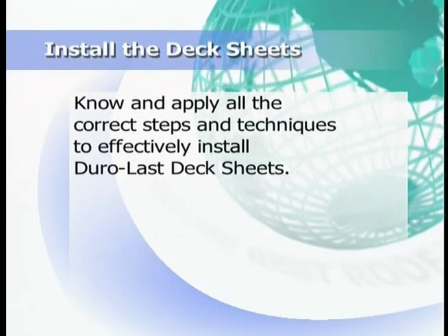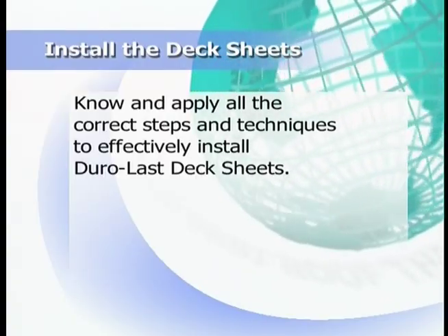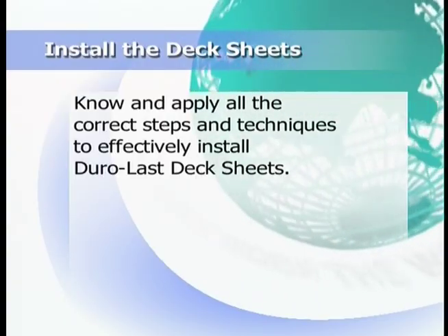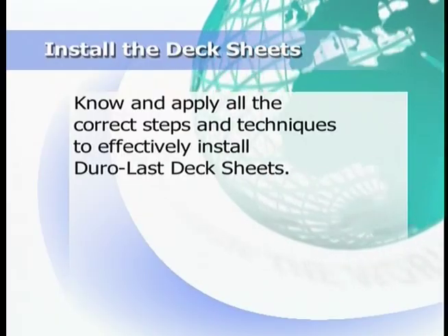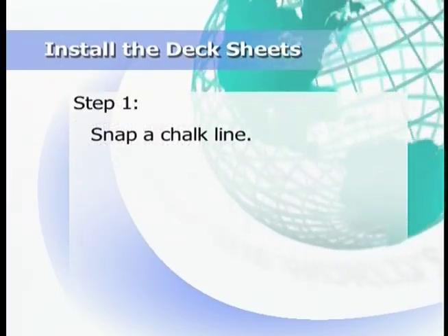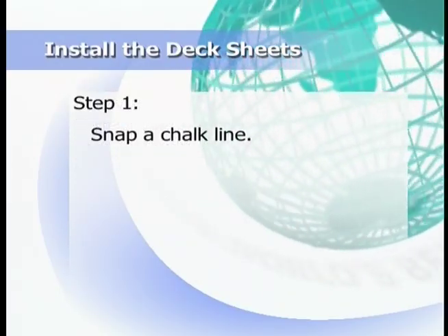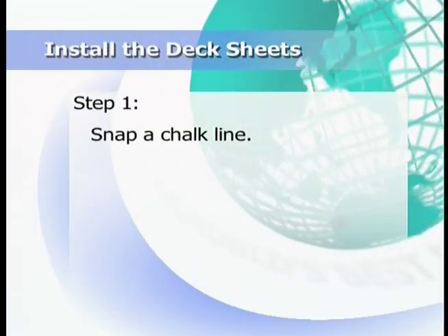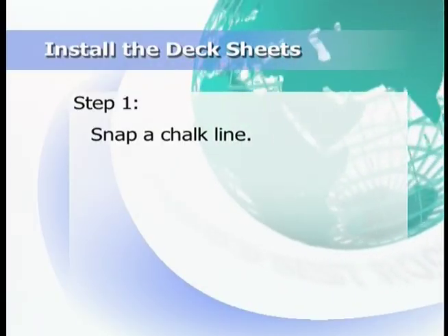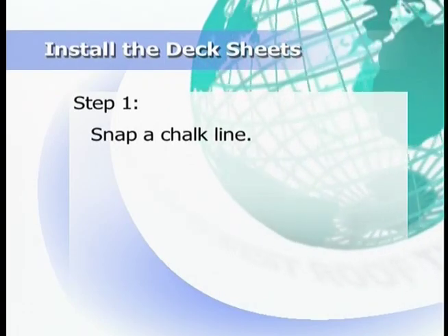When you have finished watching this video clip, you will know and be able to use the correct steps and techniques to proficiently install the Duro-Last deck sheet. The first step in installing deck sheets is to snap a chalk line so that your piece can be installed straight. There are 2 different ways to determine where to snap the chalk line.